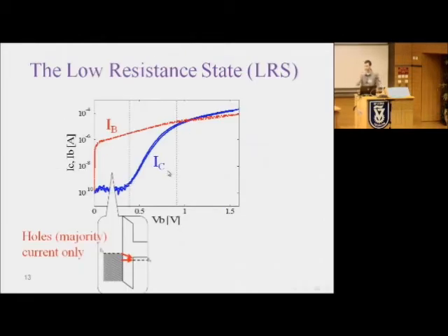I will divide it into 3 different voltage levels and start with a low bias. As you can see from the energy band diagram, in this case, just like the negative base bias, we do not expect any injection of electrons, and the collector current is negligible.